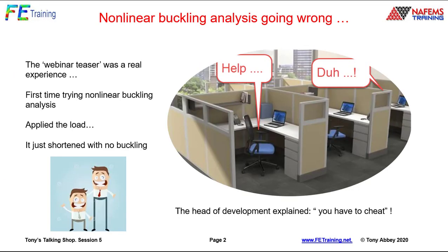Now the webinar teaser, the promo that I put out, was actually based on a real-world experience. The first time I ever tried to do nonlinear buckling analysis, I got into trouble because I just applied the load to a cylinder, and the cylinder started long and just foreshortened. It got short without any kind of indication of buckling.